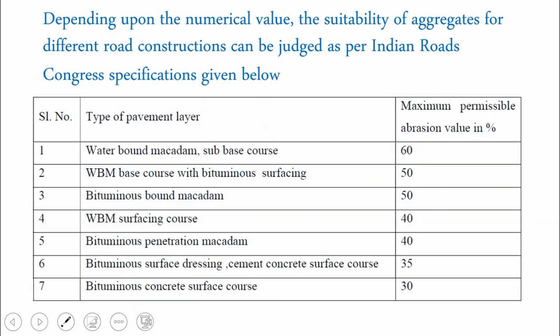Depending upon the numerical value you obtain, suitable aggregates for different road constructions can be judged as per the IRC specification given below. For water bound macadam sub-base course, we may require an aggregate abrasion value of maximum 60%.